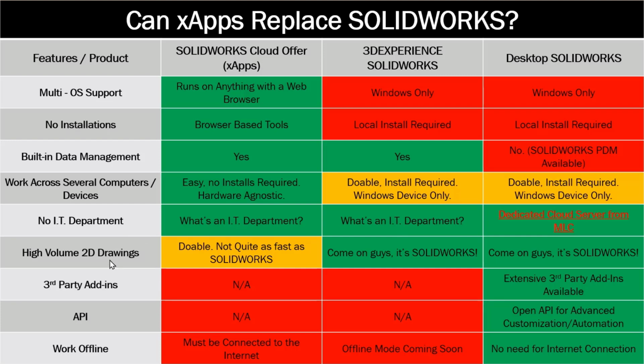Now here's where xApps might not be a great fit for you. If you're still doing a lot of high volume 2D drawings, you can still do them with the xApplications in the cloud. They're just not quite as fast, and you might not have as customizable an interface. So 3D Experience SOLIDWORKS or maybe Desktop SOLIDWORKS would still be the best bet for you at that point. The other areas are if you use extensive amounts of third-party add-ins, those aren't supported on either the xApps or the 3D Experience SOLIDWORKS. Or if you're leveraging the API, that's another area.